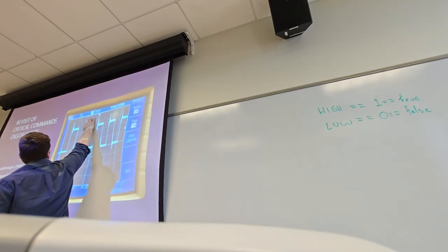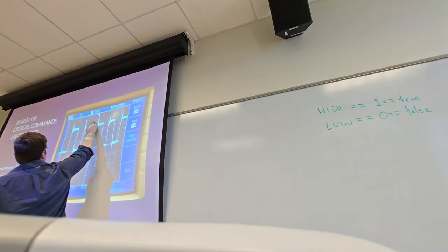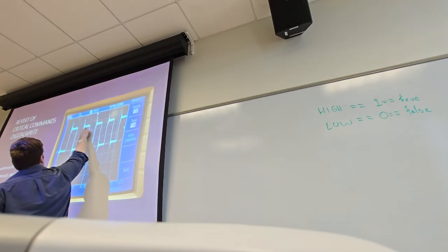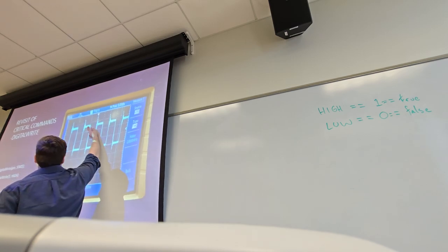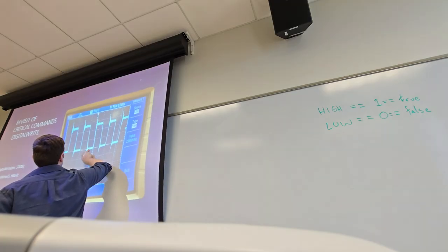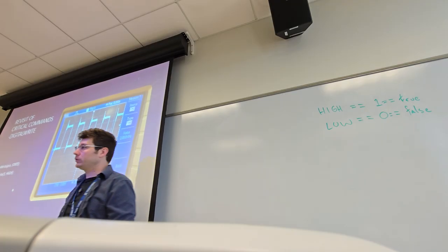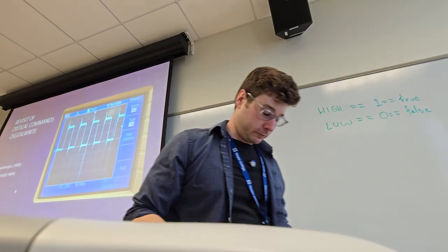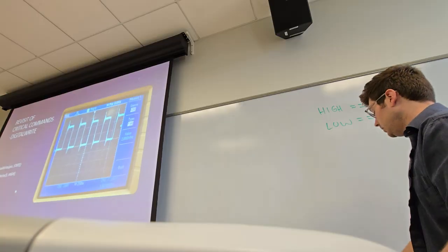We see a little bit of ringing here, that's what this is called, where we have a little bit of overshoot, but it settles down to our stable 5-volt high signal, and then we turn it off. We blip it back off. This is an on-off blip. We blip back down, a little bit of ringing down here, but then we settle at 0 volts until we go back up again. So it's literally changing the voltage on that line from 0 to 5 volts.